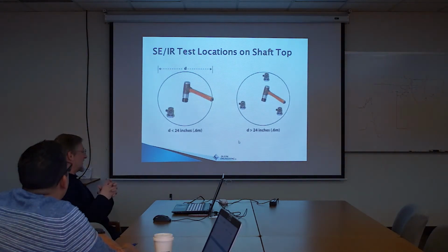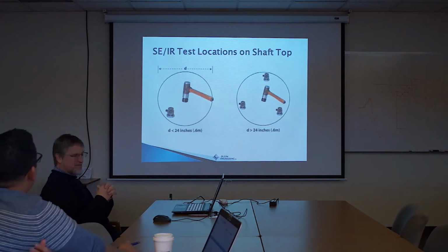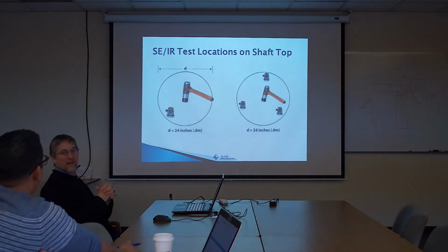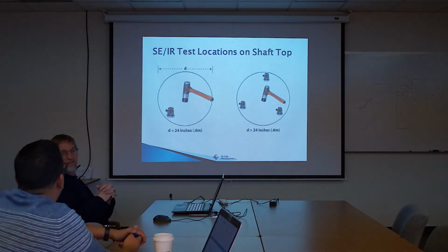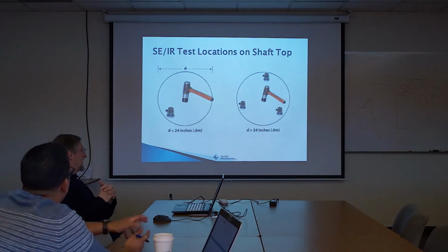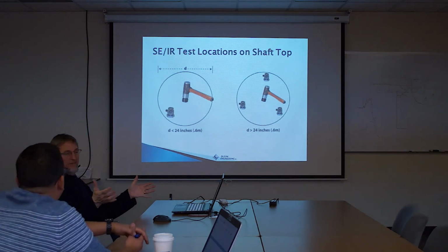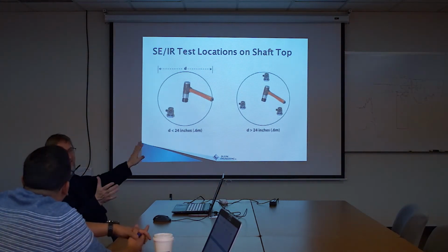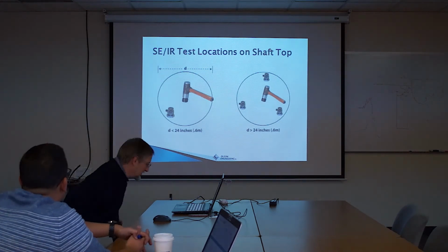Now, one thing they like, based on the ASTM standard, when you're testing for quality assurance of new shafts, they really want you to do 3 tests if it's greater than about 2.5 feet in diameter. I don't remember, I think the cutoff might be 30 inches in the standard. That's not going to be possible if it's under grade beam, for instance. For forensic investigations, that's not an issue. This is for testing a new shaft for quality assurance acceptance. That's what the ASTM standard is designed for.